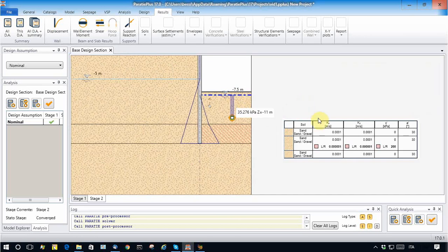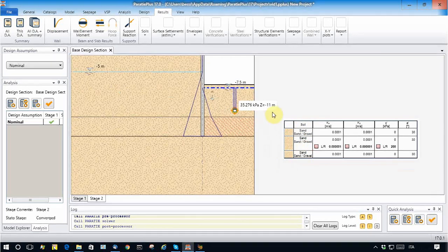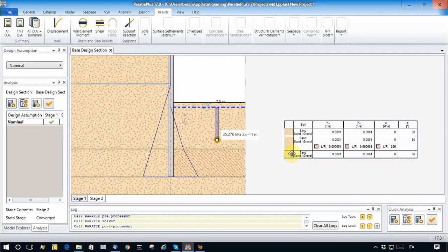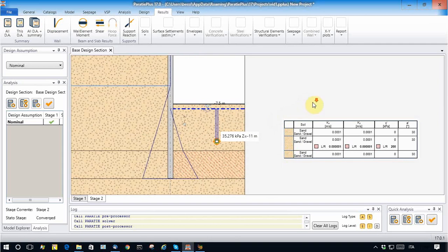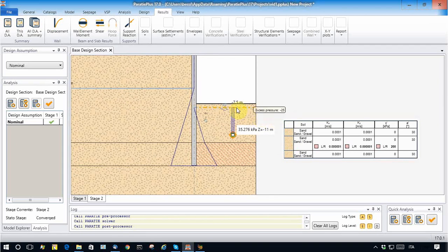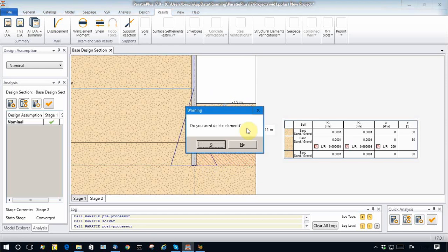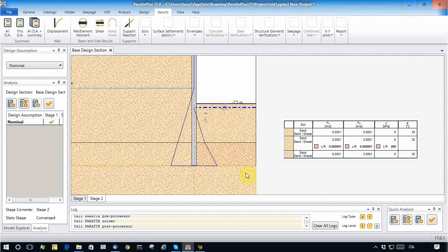in this zone, the water pressure just depends on the water table we applied in this part. So of course, now once we have reduced the requirement for pumping, our concern may be whether this zone is actually stable, due to the possibility of important uplift forces upward in this zone.